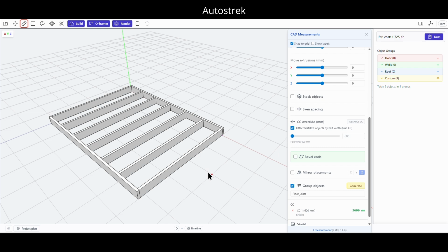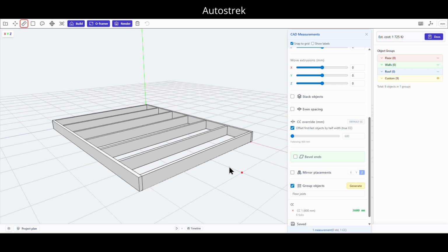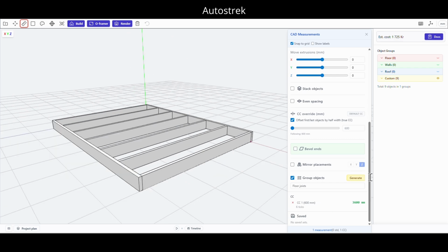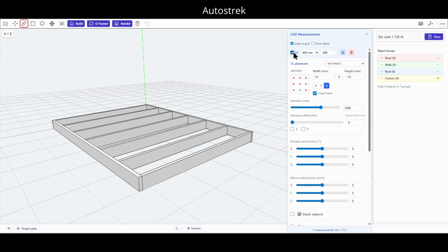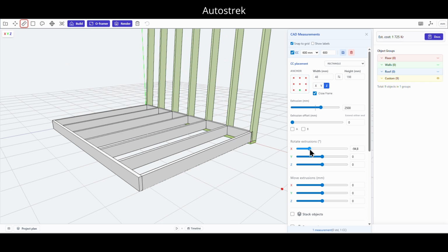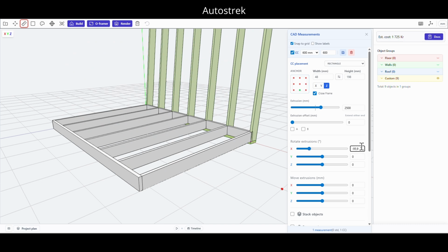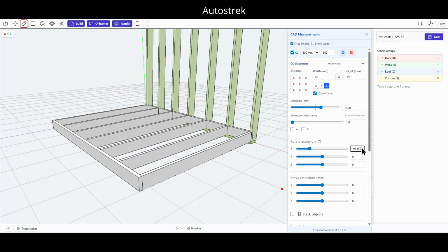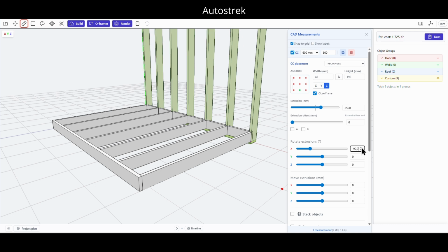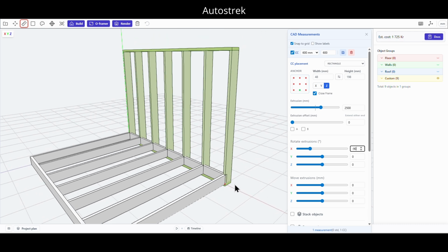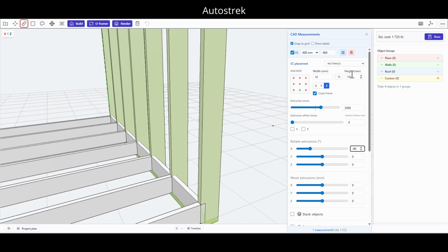The measurement is saved temporarily, so you can reuse it for the walls and simply adjust a few parameters and placement. If you toggle the CC option off and on again, the green previews return so you can edit them. Creating the wall frames is straightforward because they follow the same CC logic as the floor. Rotate, move, and adjust dimensions to form the walls.